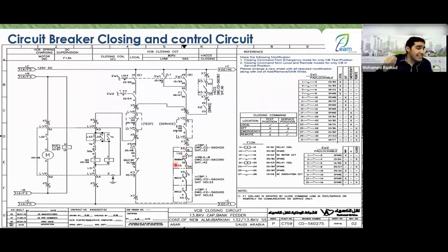So how is it reset? You must come and reset it manually. So this depends on the maintenance team. They will come to correct the existing error, check the cable, see whatever it is, and after fixing it, they will reset it manually, allowing you to reclose the electrical circuit. What happens if it was not reset? Anyone might mistakenly think the fault is gone and close the breaker, which could affect the maintenance person. He might come and not realize that he hasn't finished his work, or someone else might think his colleague has finished the job.